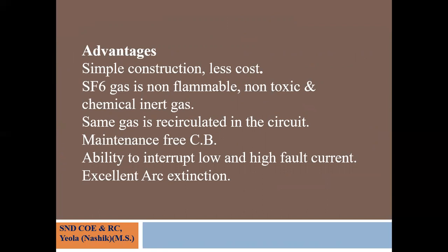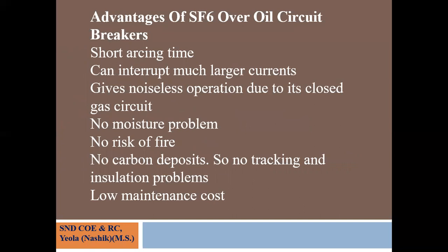SF6 gas is non-inflammable, non-toxic, and a chemically inert gas. The same gas is recirculated in the circuit. It is a maintenance free circuit breaker, with the ability to interrupt low and high fault current, and excellent arc extinction. Advantages of the SF6 circuit breaker over the oil circuit breaker.